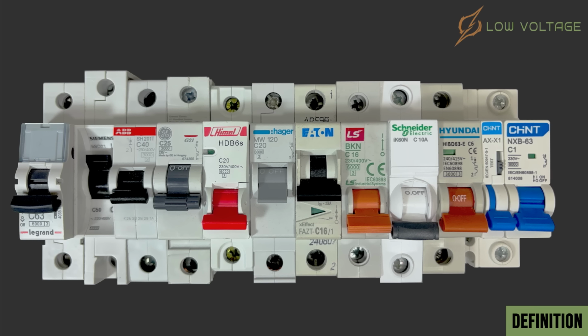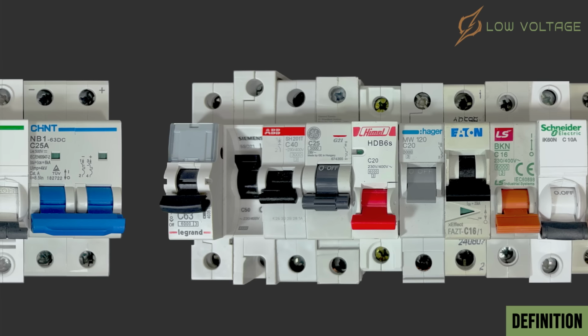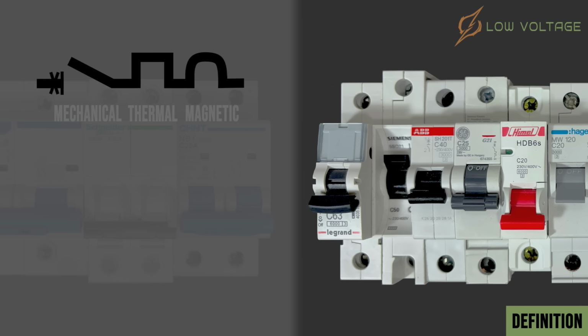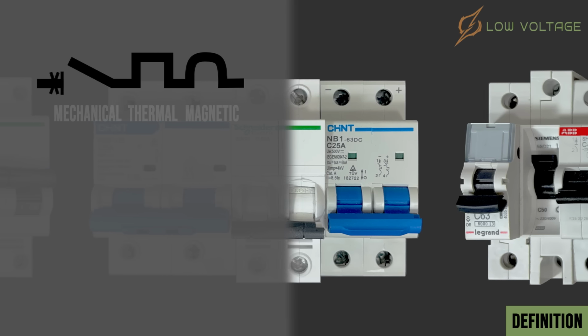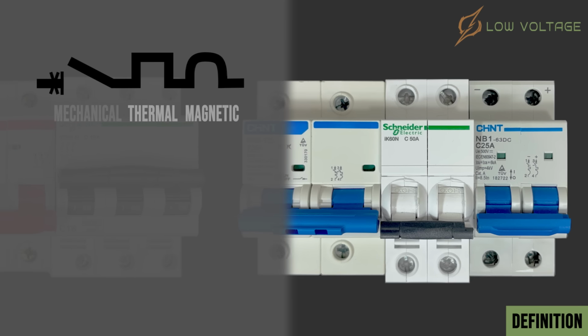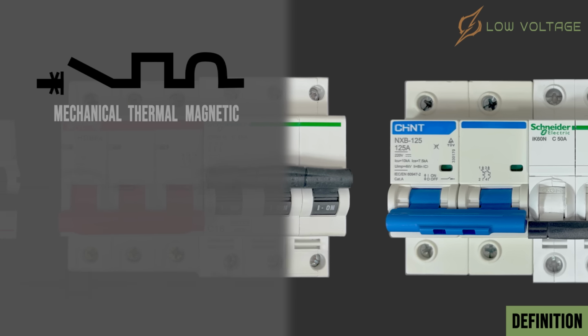Miniature circuit breaker, abbreviated to MCB, is categorized as an electromechanical device because it acts mechanically due to electrical behaviors. This is a common symbol used to describe it. The electrical behaviors are translated either thermally or magnetically, forcing the mechanical operation of the device, which is called tripping.